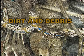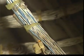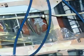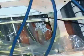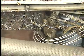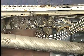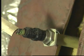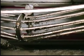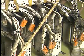Dirt and debris. Metal shavings and debris left from modification work deposited on wire bundles result in degradation. Always protect wire bundles and connectors during modification to decrease the risk of degradation. Dust is a consequence of the aging effect on aircraft. Be aware that dust acts as a humidity absorber and may have consequences. It is consequently recommended to remove dust as far as possible.